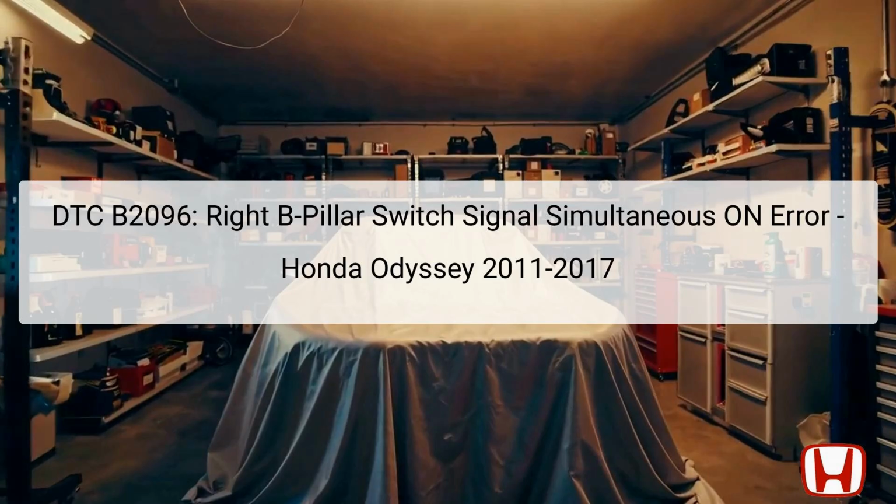When this error occurs, it generally points to an electrical fault, where both the open and close signals from the B-pillar switch are sent simultaneously, leading to confusion in the control unit and triggering the DTC. This guide will provide a detailed troubleshooting process to diagnose and potentially resolve this issue effectively.